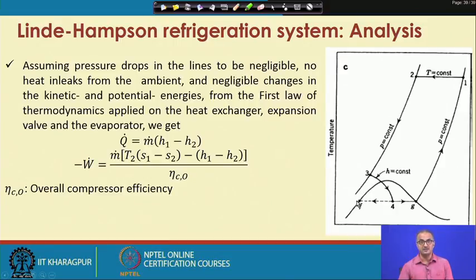And this liquid will now get vaporized, and once it gets vaporized isothermally, again it will tend to move towards the right. So all these things are not to be shown on the TS diagram, because this phase diagram is just showing the change of the phases. It is not showing the amount. The amount is not shown on the phase diagram, but we have to understand that this liquid will undergo the phase change and it will again move towards the right.